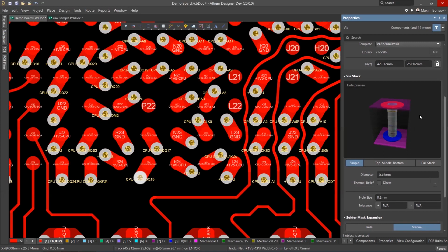And very soon you will be able to select the corresponding pad stack and just get to the physical properties of the pad shape, which is quite convenient, especially if you have a multi-layer design. You really don't want to sift through all those parameters, but you would like to visually select the actual pad on the required layer, assign a new pad stack, suppress unused, change thermals, control back drilling, things like that. Quite convenient.